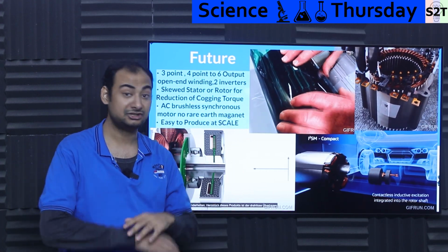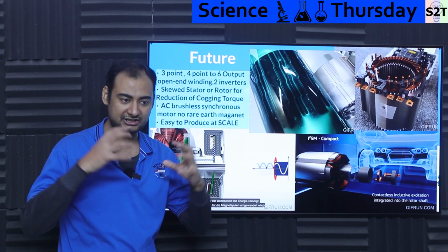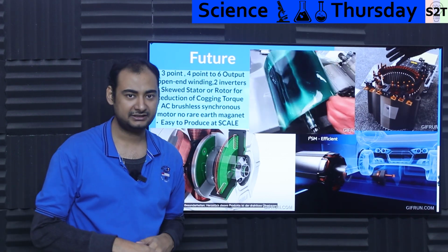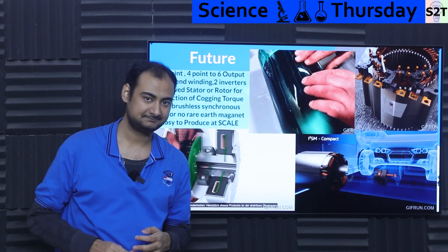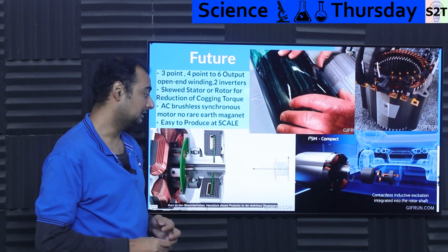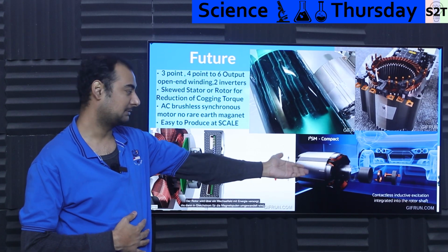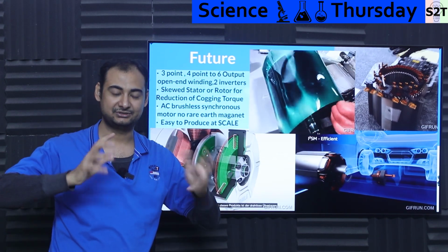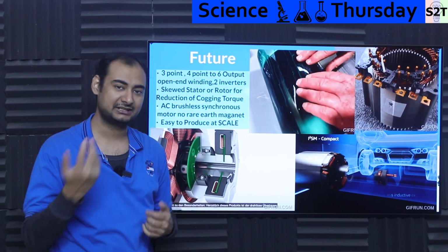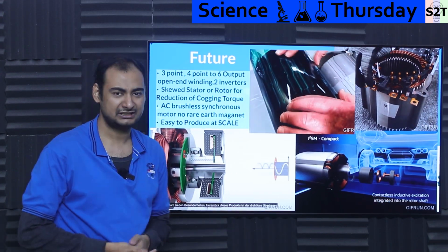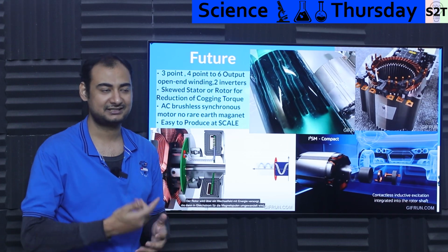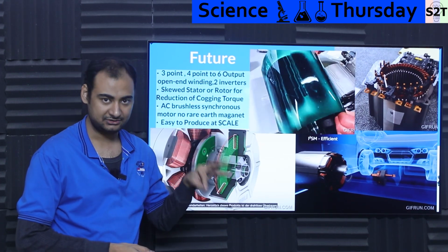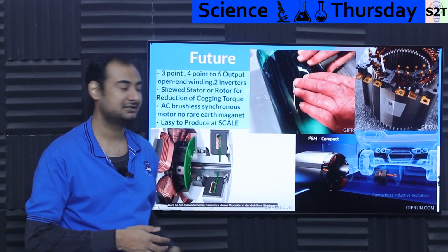Meaning if you run this motor continuously without any issue, what is the addition of motor vibration to bearing degradation? This will have the least penalty. So people want to do that. Now my love motor, this puppy cannot support that because it's too complex, but you can rotate the stator, you can tilt or skew the stator, so you can get the same effect. And again, more than enough manufacturers, especially with the round wire designs, it's like that's not an issue. So that will help reducing the noise and making sure the lifespan is increased.